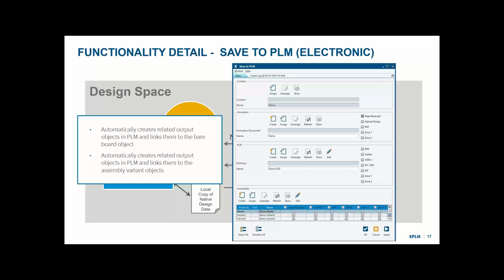I mean, if you're not sure right now, we can definitely look at it for your part, right? Let's say it's a 1, 2, 3, 4, 5. If you've got a bunch of different footprints for that part, what I've seen is you might have a -1 to represent one footprint or a -2 to represent another, if the footprint of the part actually requires it to have a separate part number. Otherwise, you would just have a single part, 1, 2, 3, 4, 5, that represents the purchasing of that part, and you don't really worry about how it's actually placed until you start looking at maybe the pick and place information or something else down the road. That might not have been the best explanation. Again, that's something that would probably be best discussed in a one-on-one demo situation.